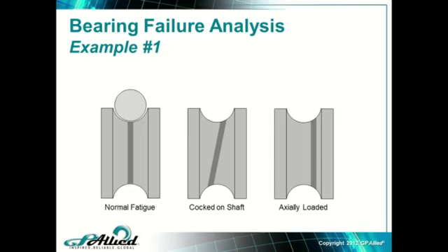So we got the crew together, and I said, look, we don't know what machine this came off of. Don't know, don't care. Don't know who did it. Don't care. I said, I just want to show you what you can learn if you pull these bearings, cut them apart, and just spend 5 minutes looking at them. And we talked about how to make sure a bearing is square on the shaft, and we talked about expansion rings. And 2 mechanics stood up and said, hey, that's actually us.